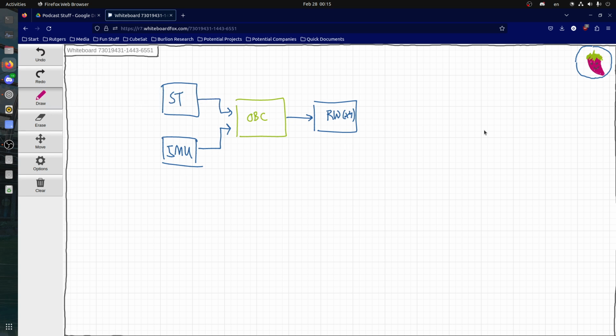You say you want to point at exactly, say, 0 degrees, right? So you're trying to point exactly at 0 degrees, whatever that means. And this is like the two-dimensional case. Your actual pointing would be like within a bound of sorts. And you would say it's like plus or minus some small amount e. For our mission, we want to minimize e as much as possible. And in here, there's actually two of them. There's e in the pointing, and then there's e in the knowledge.